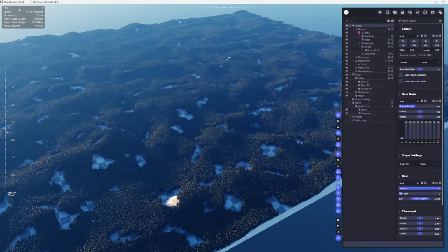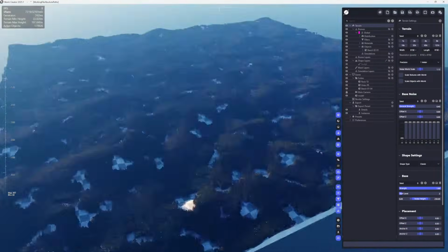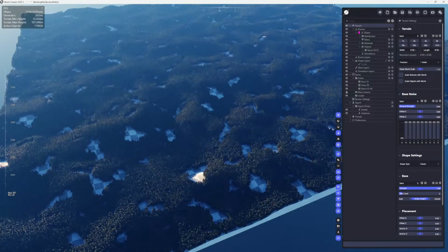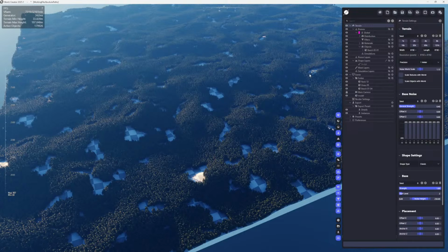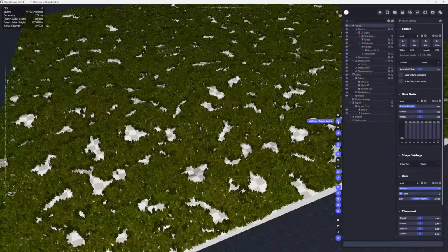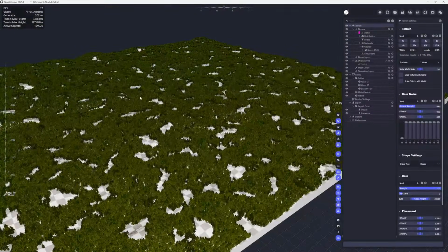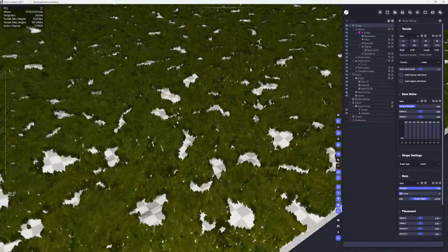So you can see that here we get a pretty low FPS, and maybe the camera is kind of laggy here. You can see that in the video. So let's see how we can optimize a few things here. The very first thing that is quite obvious is changing the render mode, because this is the cinematic render mode. This means you're getting really ultra realistic images out of it. So switch to material design mode, and your camera and your frame rate gets a lot better, okay?